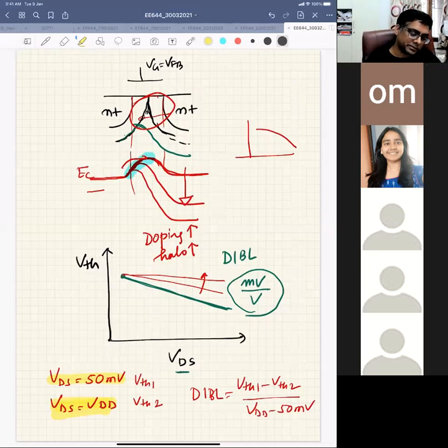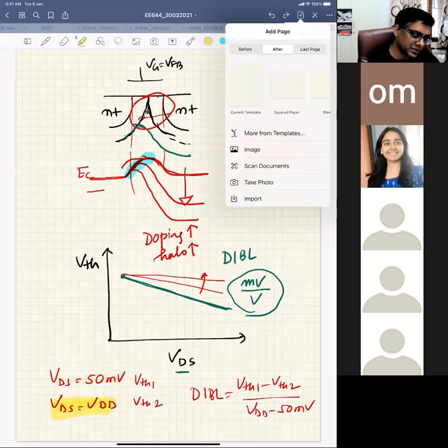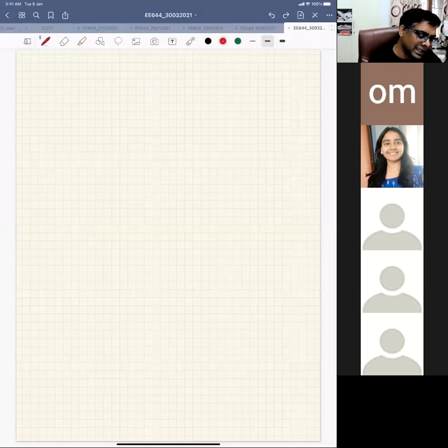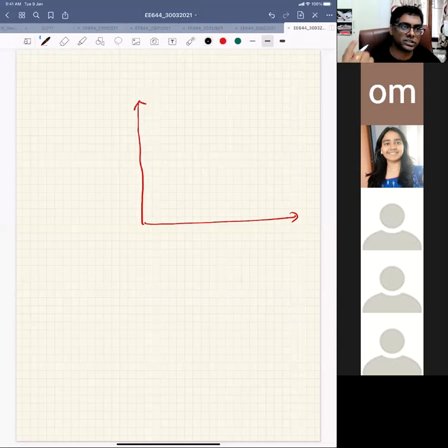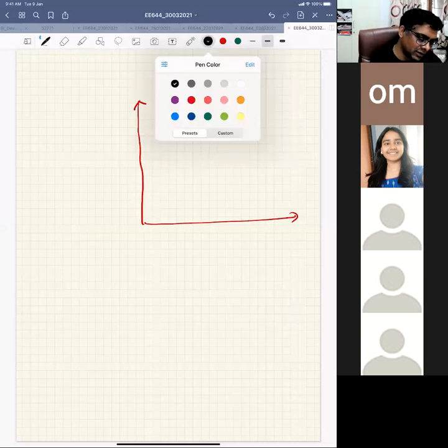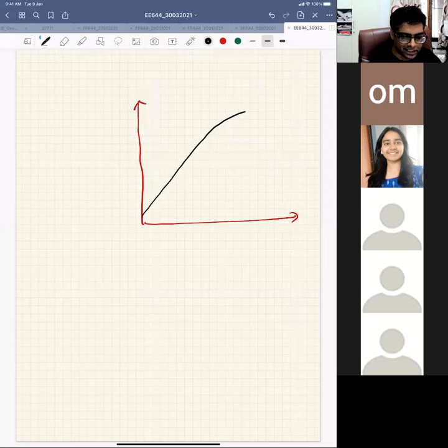Sir, these are for DIBL. Is there any specific value for subthreshold slope also? I told you how to measure subthreshold slope. Subthreshold slope will also change with VDS because of short channel effects. Let's say you have this characteristic, for VDS of 50 millivolt.